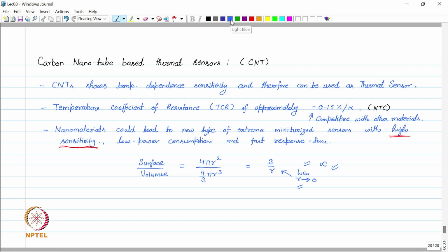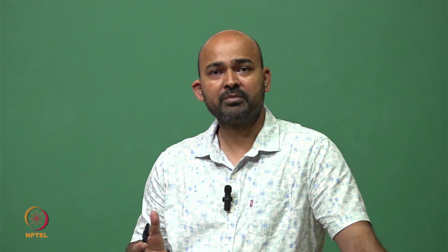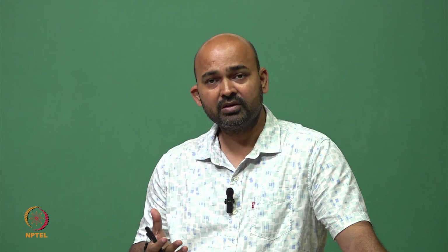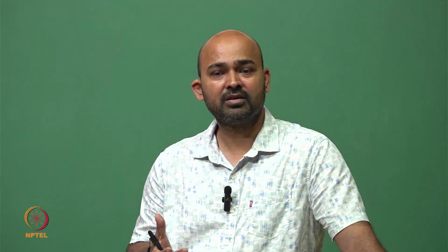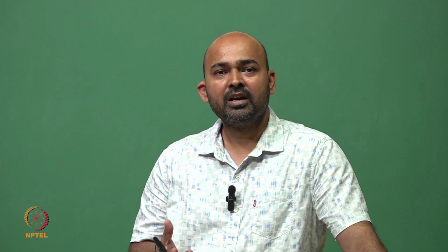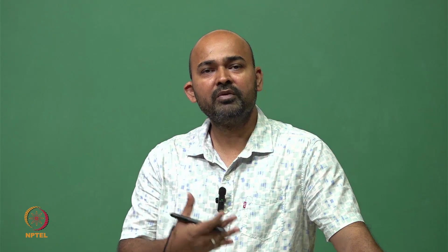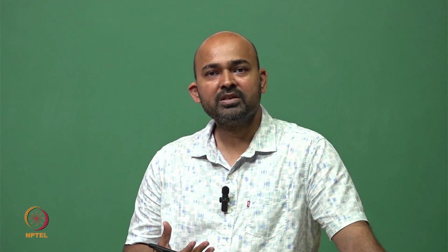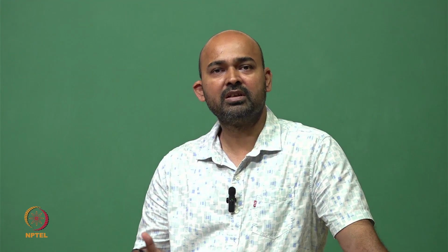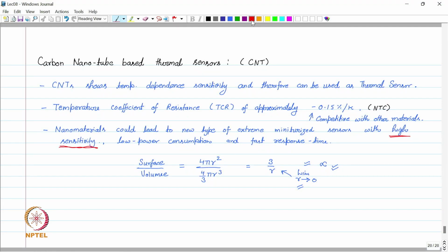The main bottleneck in the development of these nanomaterials is the integration of these materials with other microfabrication, for example silicon based fabrication, which dominates all the fabrication process. These new nanomaterials are not very compatible with the silicon process, so we cannot batch process them along with the silicon devices. So this is the limitation of these CNT based or some other fancy nanomaterial based sensors. So the limitation we can write: